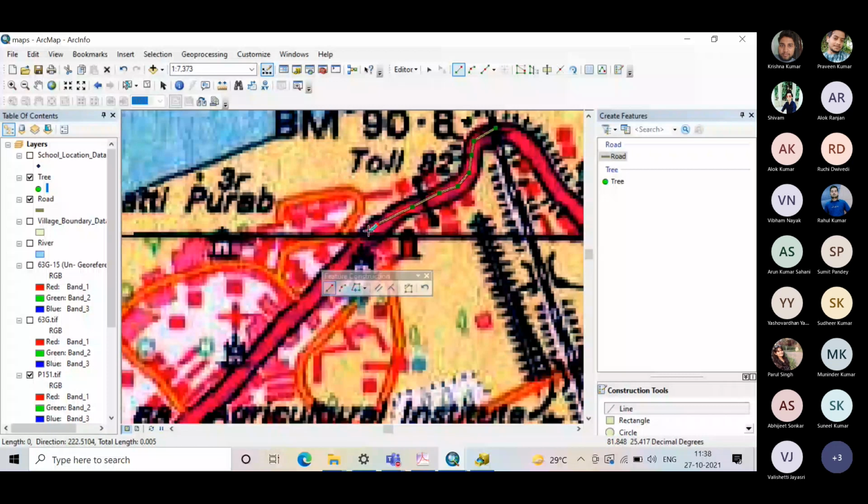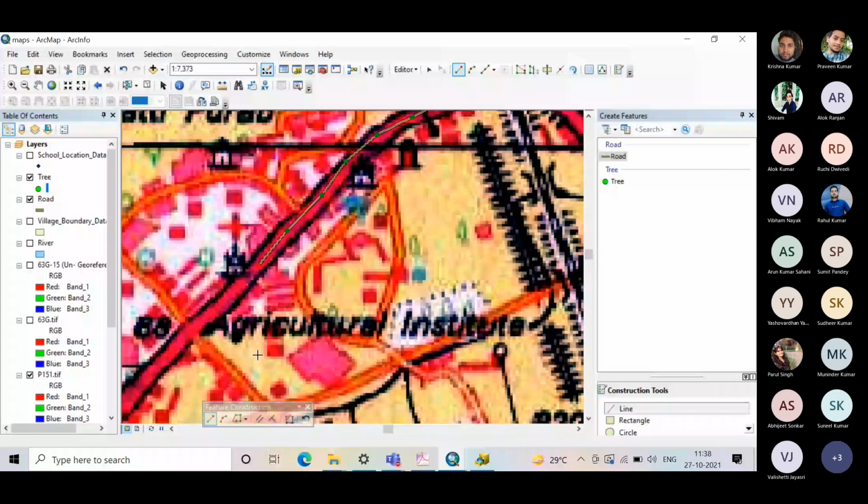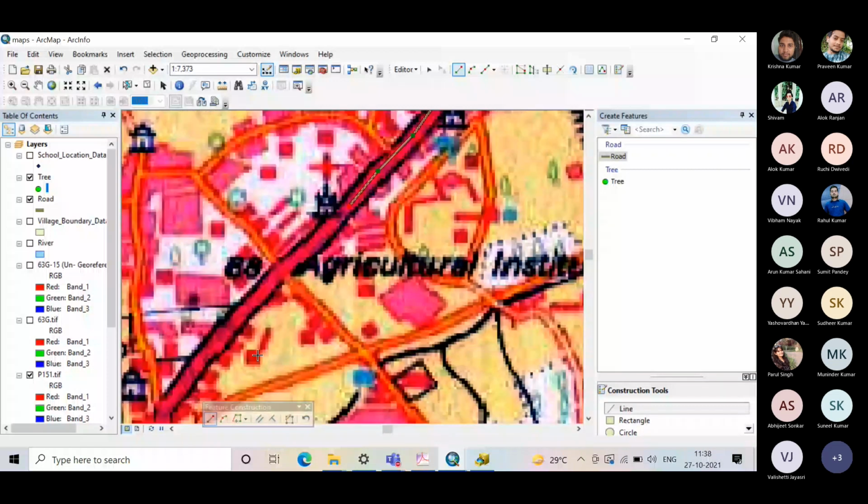In raster data, there is an issue of width over here, so the positional accuracy matters. When you are doing the vectorization from this raster data, this digitization is nothing but the creation of vector data from the raster data set. Whenever you are performing such a conversion, there will be an error. As you can see on the screen, this road is not shown by a line. It has some width, isn't it?